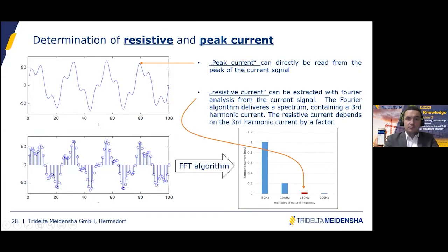Anyway, there's the slide here. It's a frequency evaluation of the wave shape of the leakage current. So what we see here is a leakage current from a surge arrestor with elevated power losses, which results in a higher resistive current, which results in a high content of harmonic currents inside the signal.